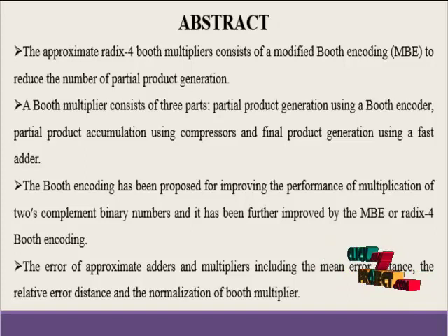The encoding plays an important role in multiplying, reducing the number of partial product rows. The approximate Radix-4 encoding level is carefully considered for the sequence of the input bits. Finally, after we design the product array and the error approximate adder, the distance-based result is normalized for the Booth multipliers.